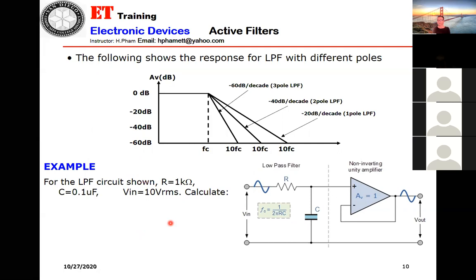He was looking for additional information. You can see they are just changing the position of C and R to make low pass or high pass. C on this side and R on the other side will be high pass. R here and C here will be low pass. Easy to recognize. That is only one pole, one R, one C. Two poles will be two R, two C.